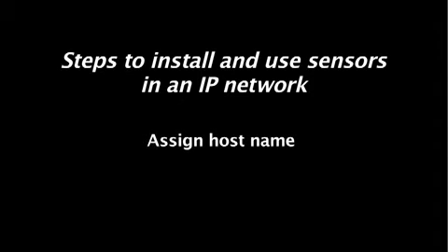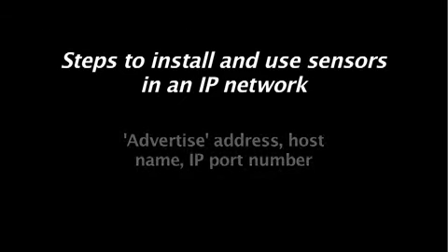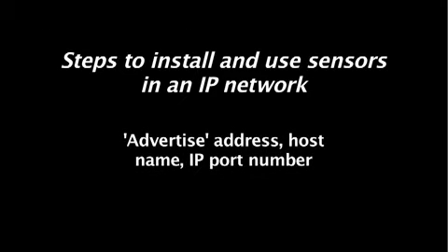A human-friendly name must be associated with the address so that users may easily find the sensors on the network. A domain name service is usually required to distribute this name. The sensor's address, host name, and IP port number must somehow be advertised to client software and human users.